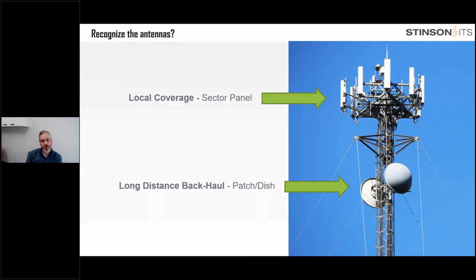It's kind of funny, but yeah, here's a picture of a standard 5G cell tower. And what you'll notice is lots of sector panels and lots of dish antennas. And that's usually what every single cell tower is made of. You'll see the occasional small omni antenna sometimes, but it's typically sections, sometimes multiple rows of these sector panels. So these are each, I think I counted around 9 of them around in a circle. So each one's probably got about a 40 or 50 degree beam width, slightly overlapping its neighbor.